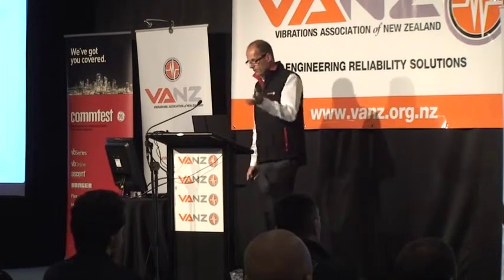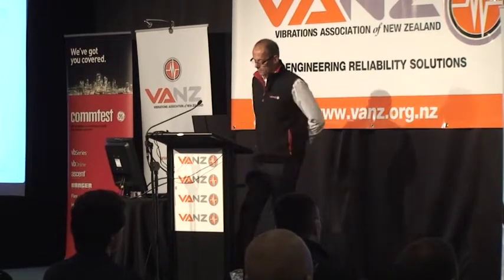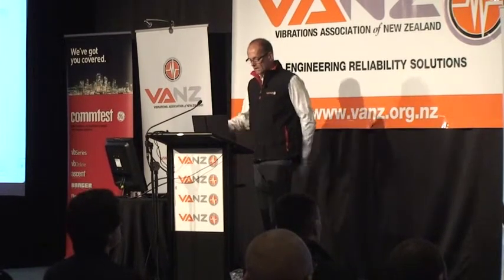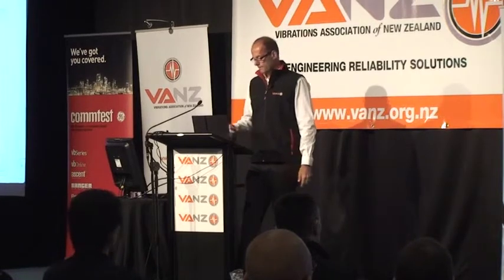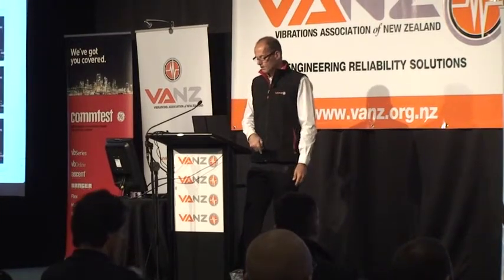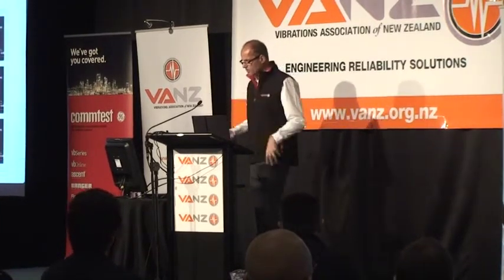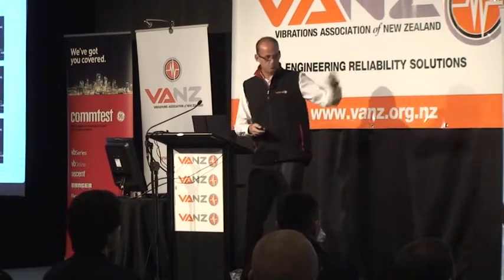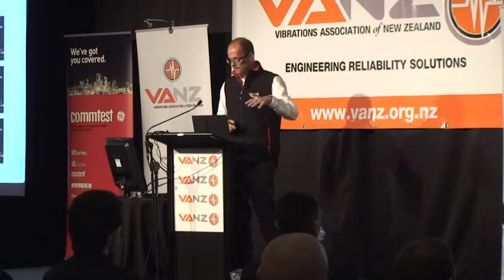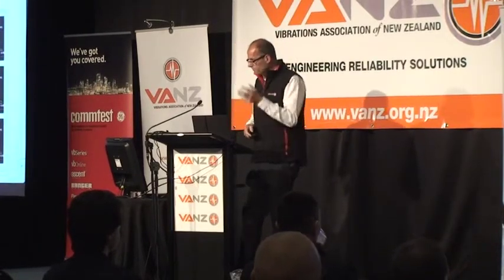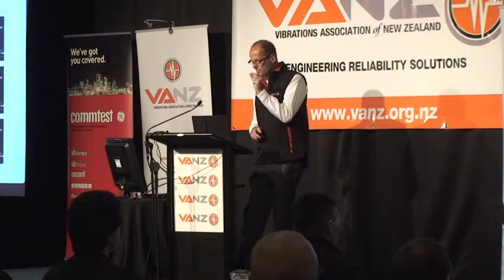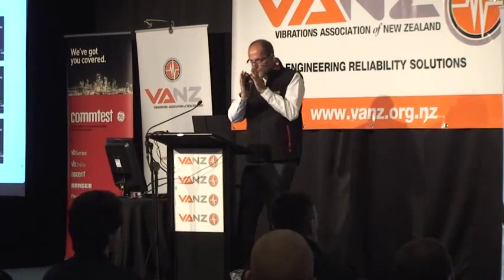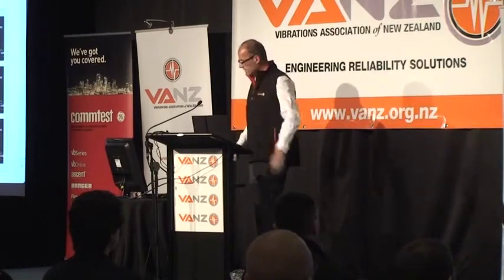This is a slightly different type of case. This is a big exhauster in a steel mill in India. And the story here was that the person sent me an email and said, "Oh, the vibrations changed, but I don't quite see what's going on." And it was just a spectrum, and you can see the peaks. There are 3 axes. You can see there are some fairly clean-looking peaks, but you notice that the peaks kind of look broad. You may not be familiar enough, but they look a bit fat. And he's asking, why is it so?